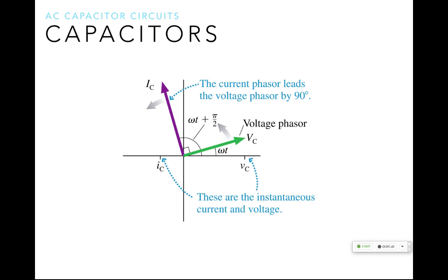Now this gets a little bit complicated because remember, what do capacitors have when you're charging and discharging them? Think RC circuits. There's a finite amount of time it takes a capacitor to charge and discharge. So if you have a nice slow frequency, it'll have time to fully charge and fully discharge. But what if you go fast? It's going to start charging, and then the polarity of the current and voltage from your source switches, and then it's going to start discharging, and then it's not going to quite have time to do that, and then it's going to start charging, right?